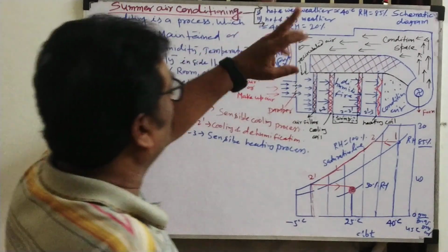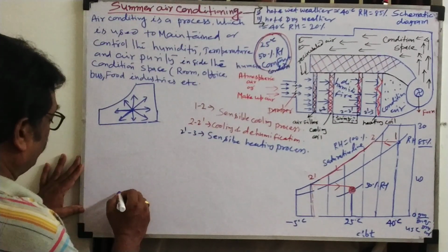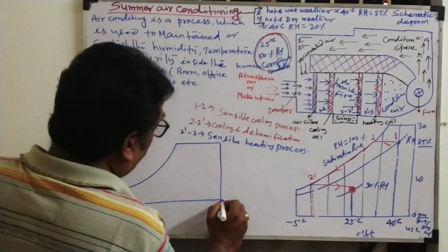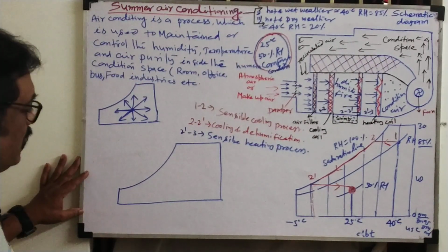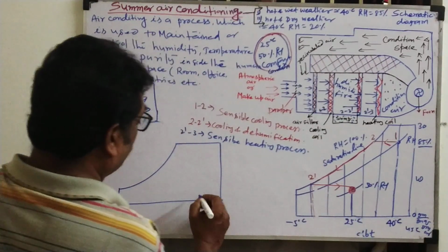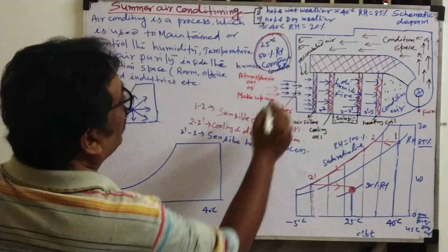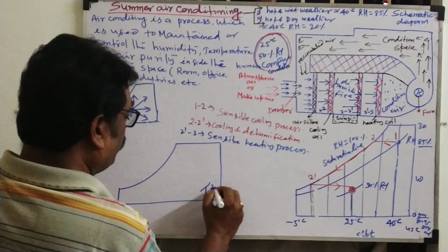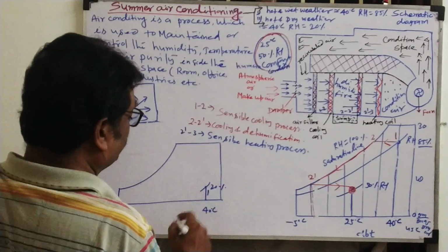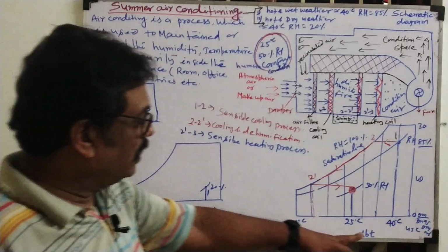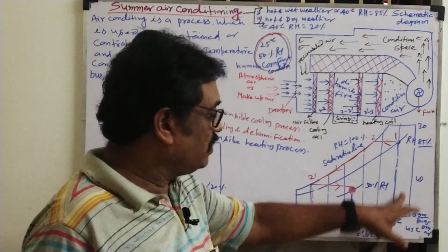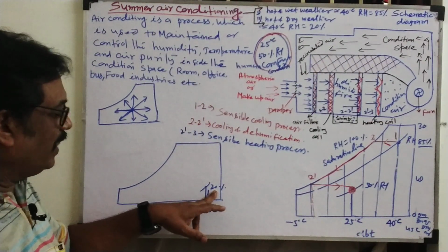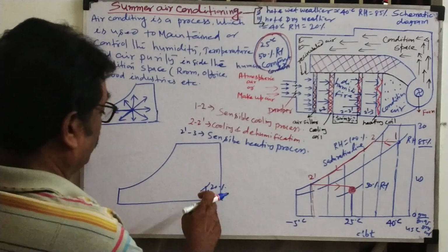Now if you look at hot and dry weather, I will explain the psychrometric chart again. Hot and dry weather, listen here. The same diagram will be there. The first condition I have taken is approximately 40 degrees, and the relative humidity will be 20%. Now see the first condition here. For hot and wet weather, the first condition is here, that is called the south zone. This is the north zone, which means humidity will be very, very low. That means dry condition.